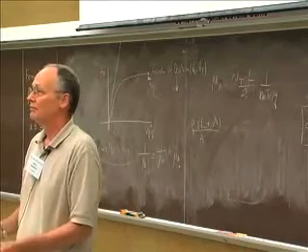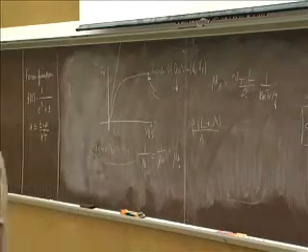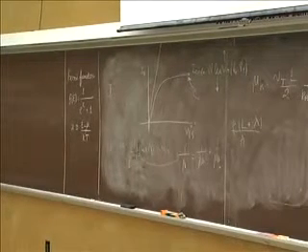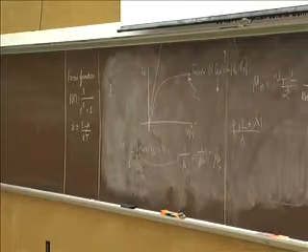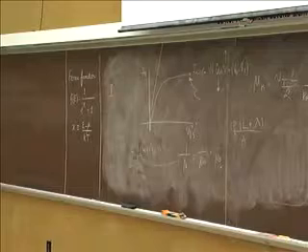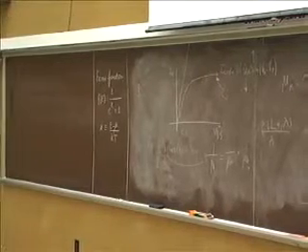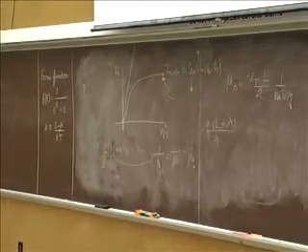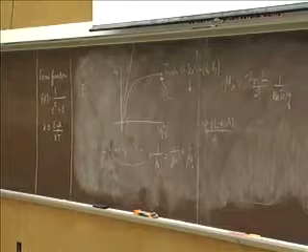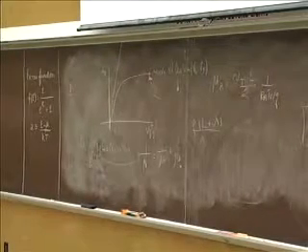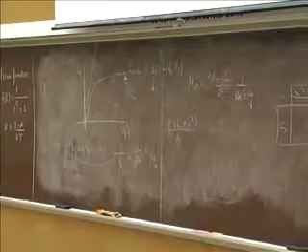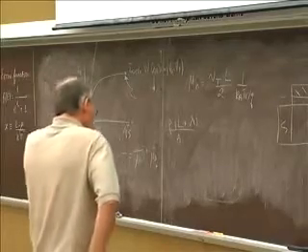Okay, anything else I can add to that? In the ballistic mobility, the thermal velocity Vt, so what's the effective mass we use? Is it the effective mass in the metal or the effective mass in the channel? Because it's the injected electron from the source, right?